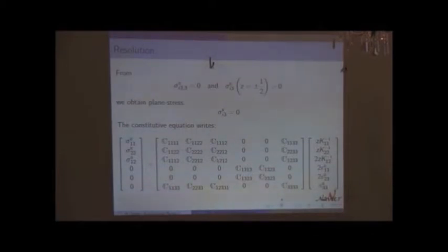No, in Kirchhoff, if you assume Kirchhoff kinematics, typically the Kirchhoff assumption is U_i is minus z with my convention, and U_3. If you compute the strain related, not from the constitutive equation, but from this Lagrange multiplier, you get the shear. You don't get it from the constitutive equation, but you get as a Lagrange multiplier the shear.